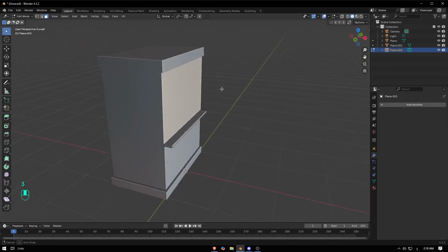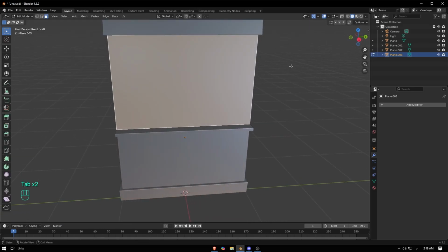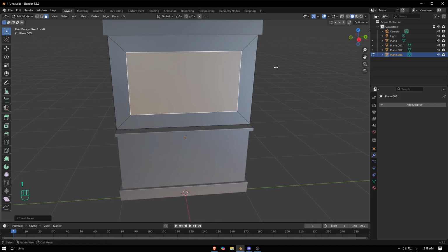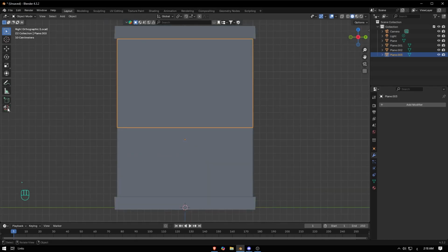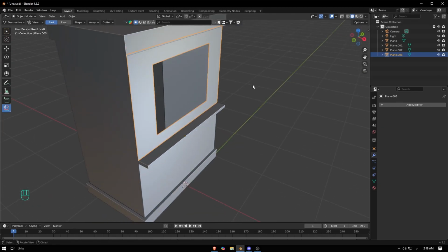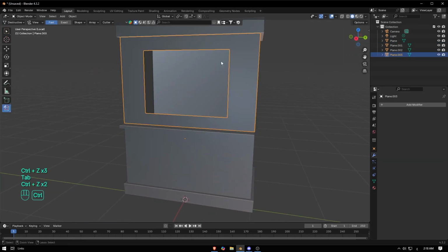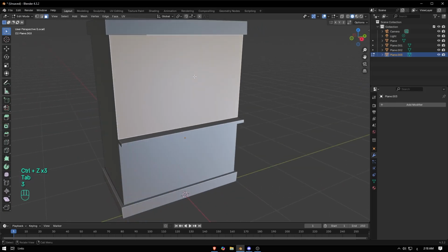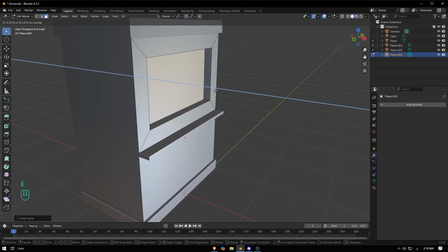And then we're going to go with this face here. Now we need to separate it again and just select this one and go with I to insert face. Or we can just use the pull tool. I think we have it. The boolean here. In Blender 4.3, I can use it like this to make my cut. I to insert face. Something like this one. Go E for extrude.